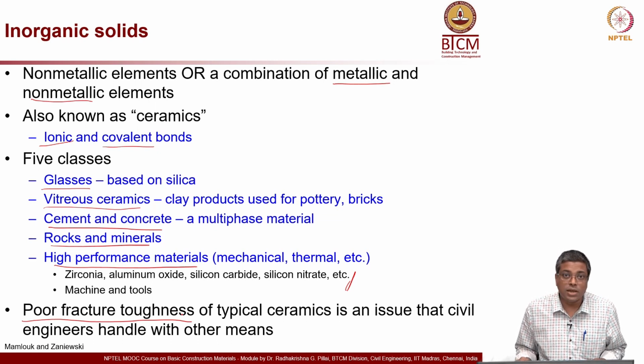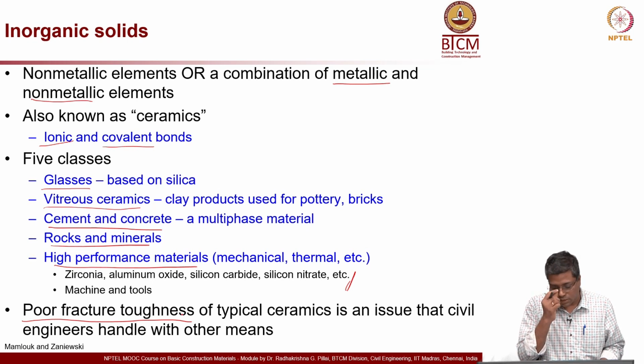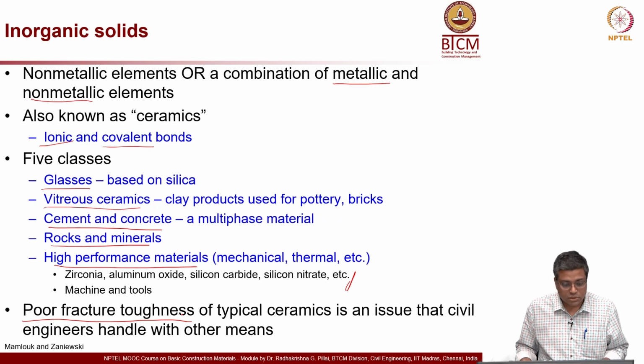So, the steel rebar takes care of the tensile properties required, and the concrete takes care of the compression, and also the steel reinforcement helps in increasing the toughness as compared to a plain concrete system. And also we have now fiber reinforced, which we discussed earlier. Different systems are available to increase the toughness.